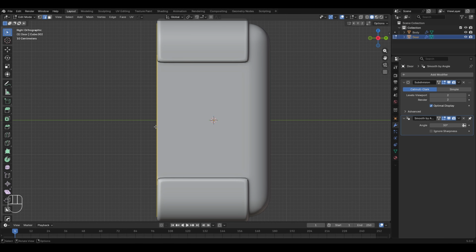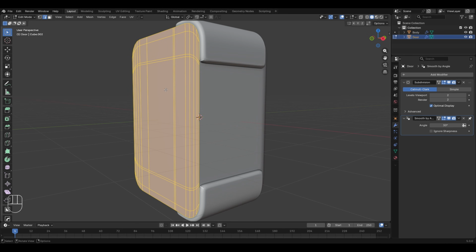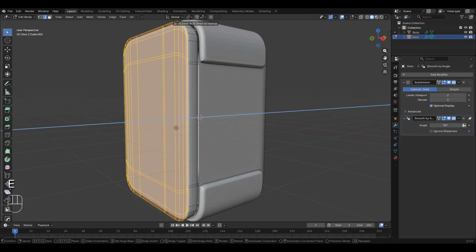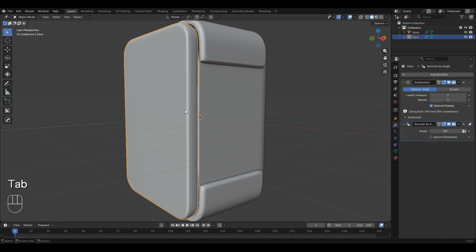It's a completely flat, plane-like object, and to give it some thickness, we'll use the extrude tool. But before that, just to ensure that all of the edges are selected here, you can press A to confirm this, and then press E to extrude this, let's say till over here. Now I'll press Tab to return back to the object mode, then right click to apply shade smooth. This will make these edges that were previously flat smoothly shaded.